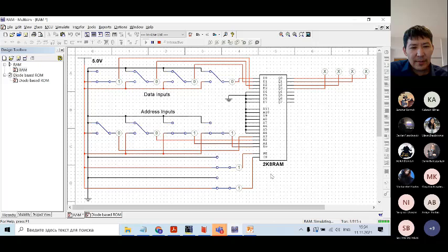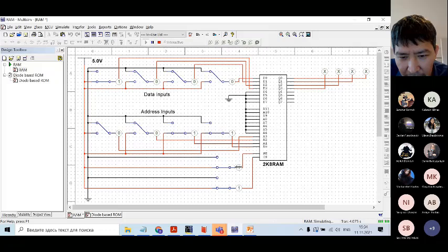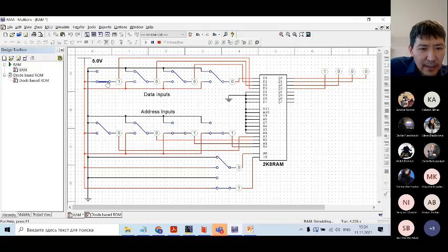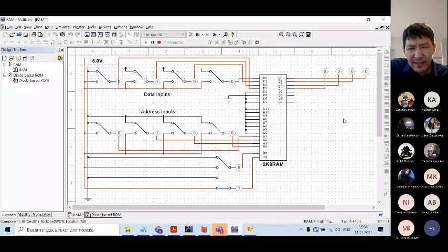Okay, so next, what I need to do? Next, I need to switch off write enable. So guys, I will change the address. You can see now I'm referring to 0000, the first word, right? But I recorded decimal 8 to the address 3. So let's read this information.